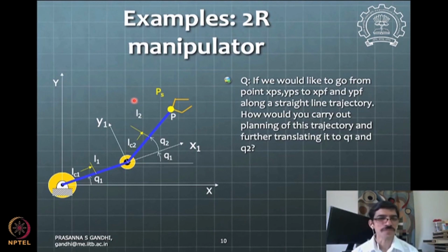Okay, so you assume some kind of inertia for these elements and things like that. So this will typically be an iterative process. Say if you are designing the manipulator itself, quite a few parameters are going to be unknown to begin with. And so you'll start off by assuming some ballpark figure values, or you keep them as variables, and then you keep on simulating and changing.